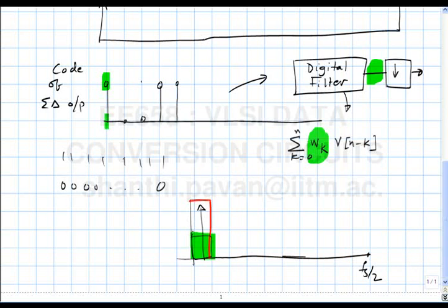You understand? So you're taking a poor quantizer which added noise all over the place, cutting off all the stuff outside your signal band, and the in-band signal to quantization noise ratio looks like a more precise converter. Is that clear? No? Almost.